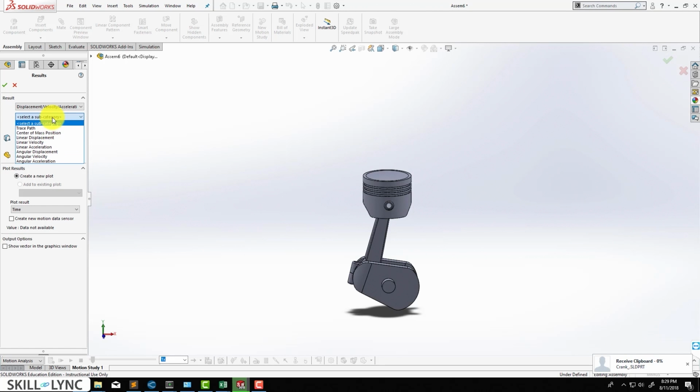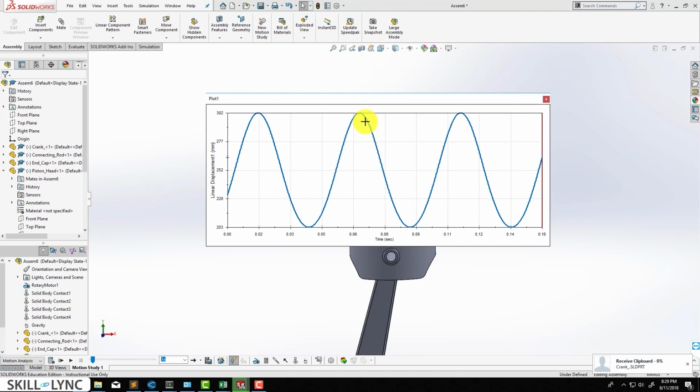There you go. When you do this, you actually get a very smooth looking plot for the displacement. Based upon the bore and stroke, you can convert it into a volume trace as well. If we use a lower frames per second, then we might not be able to capture the maximum and minimum value for the linear displacement. In fact, that is something that you should try out.